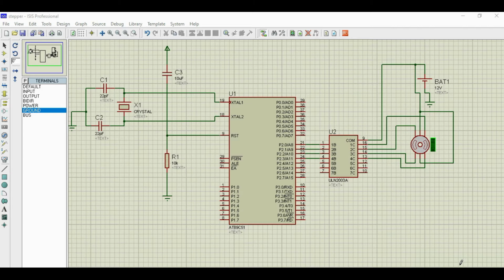Here we can configure the stepper motor to rotate clockwise up to 180 degrees. Let's provide some delay for the person to enter the room, then close the door to its previous position. So positive clockwise 180 degrees, then negative or anti-clockwise 180 degrees. That's our procedure.